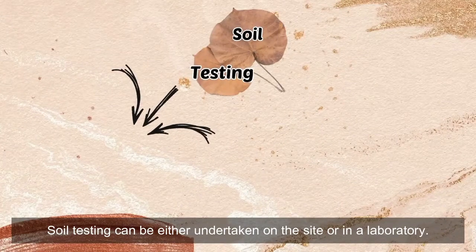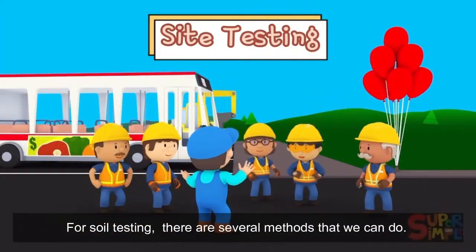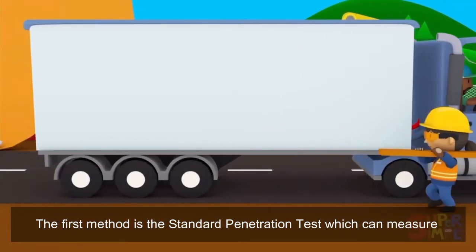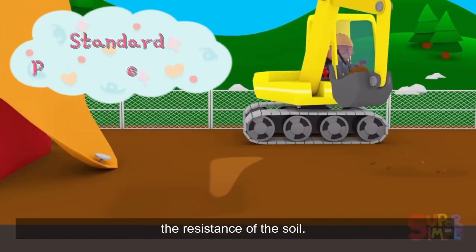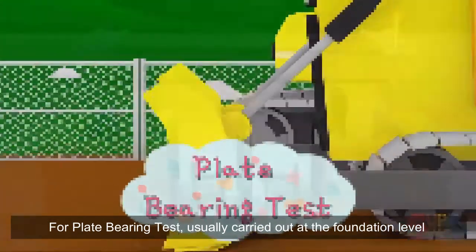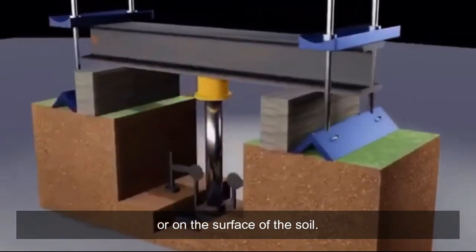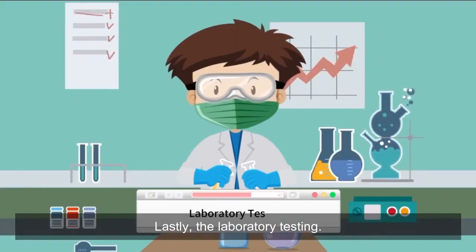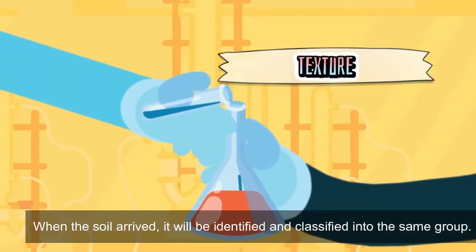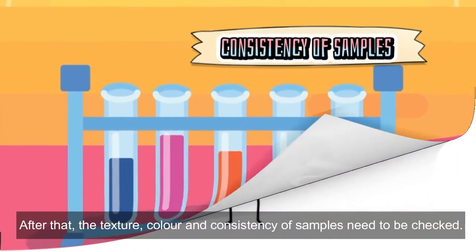Soil testing can be undertaken either on the site or in a laboratory. For soil testing, there are several methods that we can do. The first method is the standard penetration test, which can measure the resistance of the soil. Secondly, the vane test is a method that can measure the strength of the soil. The plate bearing test is usually carried out at the foundation level or on the surface of the soil. Lastly, laboratory testing. When the soil arrives, it will be identified and classified into the same group. After that, the texture, color, and consistency of the sample need to be checked.